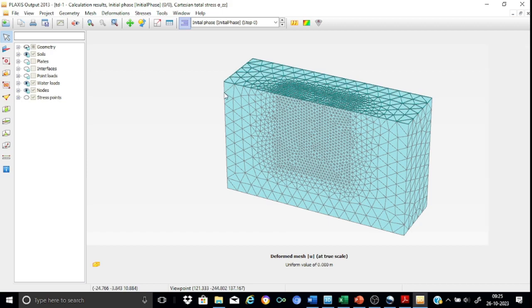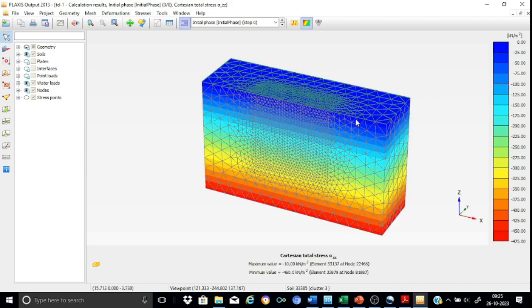Okay, so here you can find that yes, the stress distribution is already shown under self-weight, and the maximum value of the stress is 460 kN per meter square. This is something like against 450 computed by hand. So this is acceptable to us. So let us quickly go to the other important one, that is when the entire pullout is applied horizontally, that is the load angle at 0.